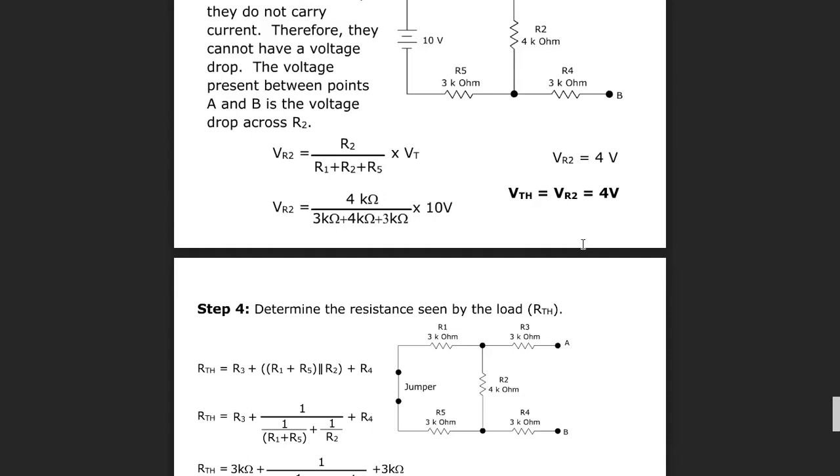In any circuit, a source delivers its maximum power when the value of the load resistor is equal to the internal resistance of that source. Internal resistance of that source, we can also call it all of the resistors which the load resistor sees or suffers from the whole circuit.